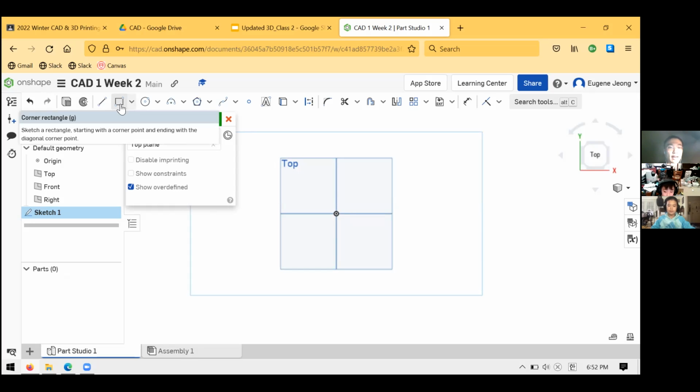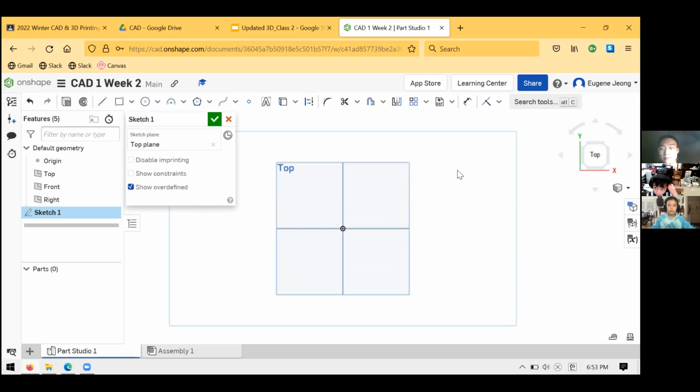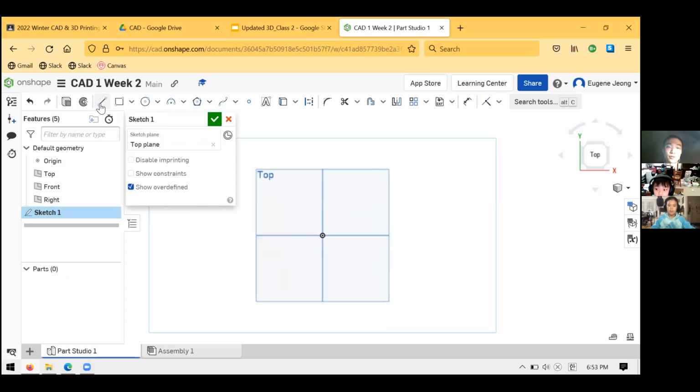If you look at these options that you have, you can hover over them to see what they are, and you'll end up using most of these. I guess the longer you work with CAD, you'll probably use all of them eventually. But I'll just demonstrate the first couple. The very first one you'll see is Line. And the way you enable a tool, the way you tell Onshape that you want to start using the tool, is you click it once. And now when I move my mouse away, you can see that the line tool is highlighted.